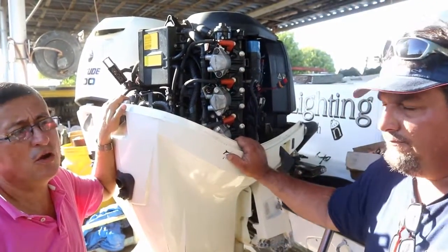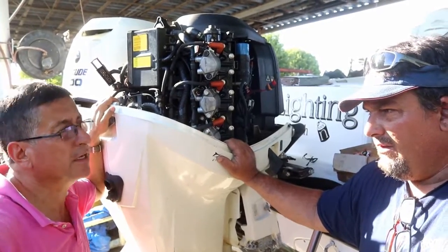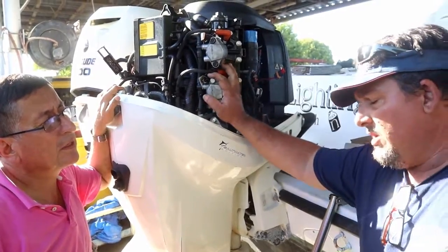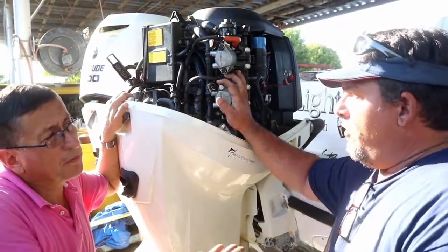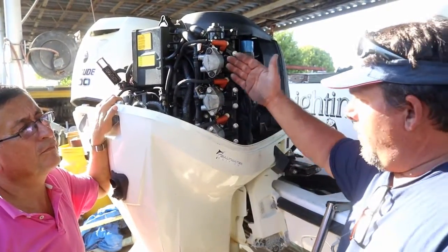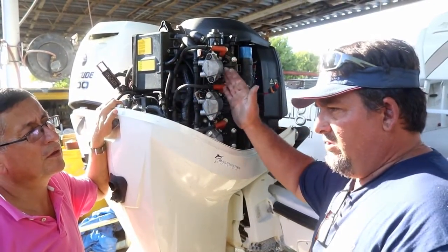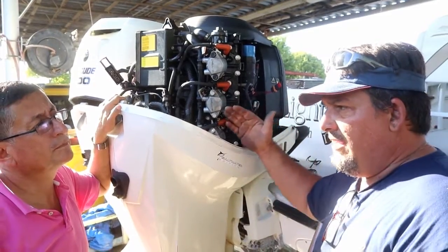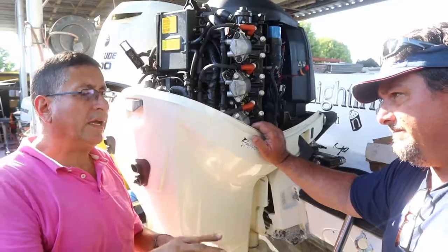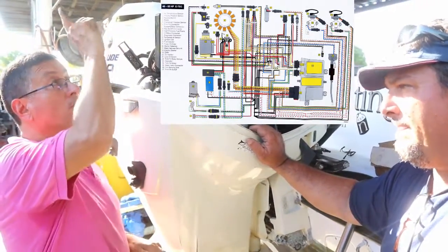Correct. Another typical question is about misfiring. Let's say you have a bad injector, it'll give you a misfire, or a bad spark plug, a bad wire, maybe one of the wires from the computer to the injector is chafed and grounded out. You have to know. That's why it's important to have a service manual and the wiring diagram.